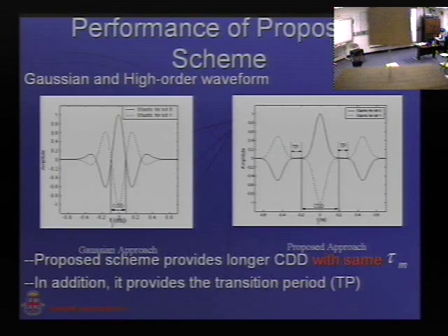Go ahead. In the previous slide, are we assuming that within the CDD an error cannot occur? You told us that when you go outside the CDD you have a possibility of mixing up 0 and 1. Can't that occur within your CDD? No, it will not, because within this region you can detect the correct information. Out of this region, in our case, we are pushing it a little further. So overall, this is what the jitter can tolerate. For us, we try to make it a little more jitter tolerant. For them, once you go out of this region, good luck. You will definitely get the flip.